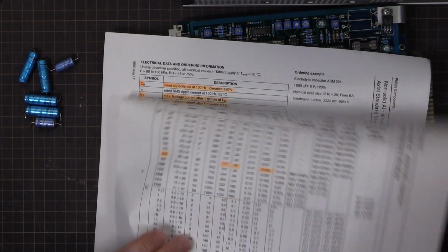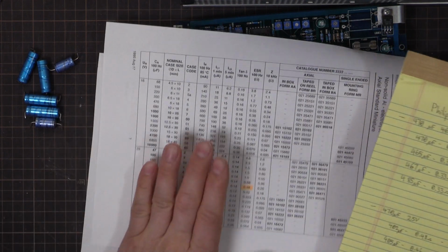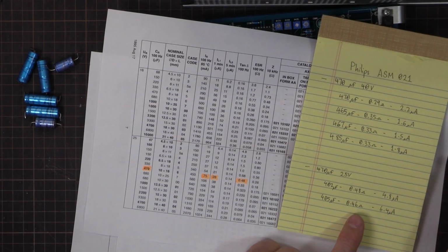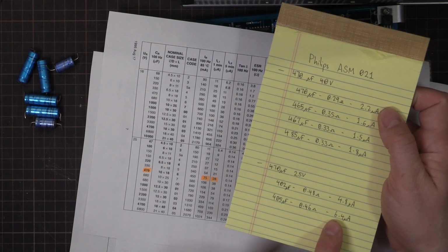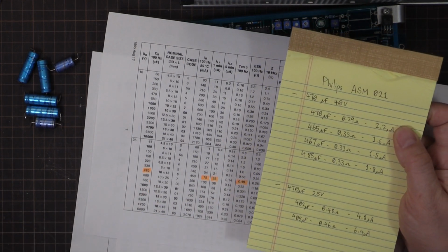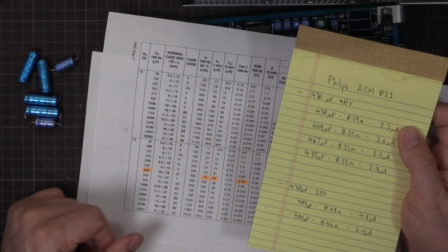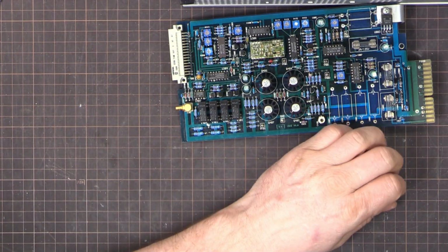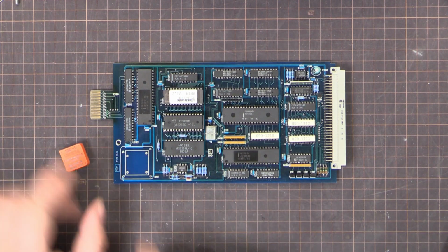And it's the same story with the 25 volt ones. The 25 volt ones are a little bit closer to their rated specs. So the ESR is at 0.48 ohms, and we got 0.48 and 0.46. And the leakage, 28 microamps, and we're at 4.8 and 6.4. And the capacitance is 402 and 405. So that's well within tolerance as well. So these capacitors are perfect, ready to go in the circuit board and keep doing their job. I'm not going to replace them.